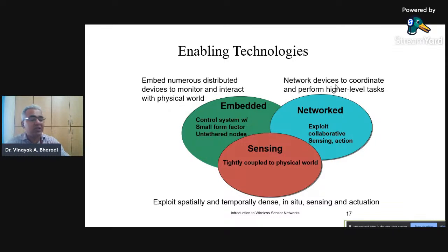So that's why these embedded devices, these are systems with VLSI and embedded devices. They are very common and have wireless and internet connectivity. So embedded and network devices are possible here. Then sensing: this device has onboard ADC, digital lines, analog lines, and small and powerful sensors are available. I showed you this BME280. This is a compact sensor, the size is very small, and its power consumption is very small. They are cheap also, around 300 rupees you get this BME280.